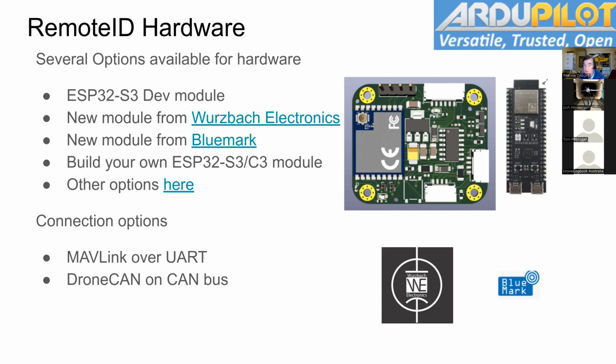And you've also got to be concerned about the proximity of this to other radio emitting devices in your vehicle, because if it's within certain, what distance is it, Jeff? If it's within like 30 centimeters of another radio, you've got to do an extra FCC thing. 20 centimeters. Okay. And that's the threshold for co-located transmitter.